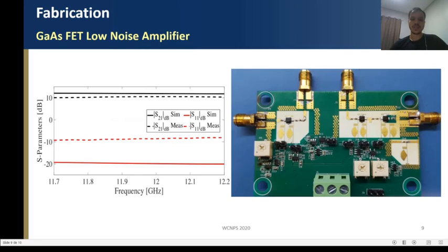A single-stage Ku-band LNA using the transistor CE3512K2 was designed with 10 dB measured gain, for future minimized cost of the active radio frequency front-end PCB.